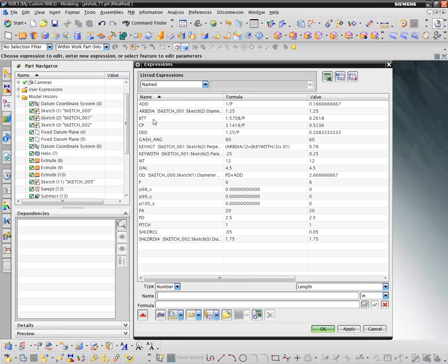Here's a number of different other formulas. Here's my circular pitch, CP. Here's my dedendum value. Now this gash angle, I'll explain that in a little bit. Key height, okay. Key width. So if I want a 1/2 inch key here rather than a 1/4 inch key. Here's the number of teeth that I want on the gear that I want to cut. So this enters into some of the formulas that go along with creating the hob.